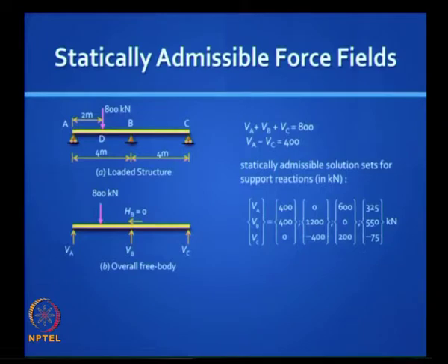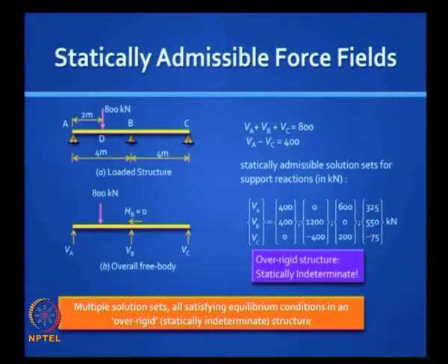The only way that could turn out to be a correct solution is if there is no contact, which means you will probably get a deflected shape which looks like, can you see the first deflection shape, the dotted line? That means there is no contact. It is like there are supports only at A and B, and the beam will definitely lift off from the support C. Then you could get this solution, there is nothing wrong with that, but it is not kinematically admissible.